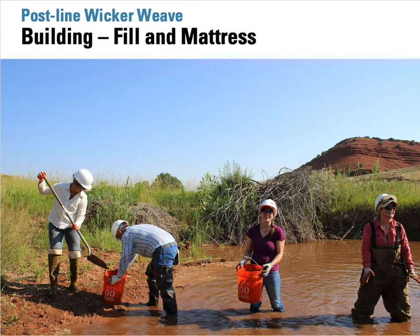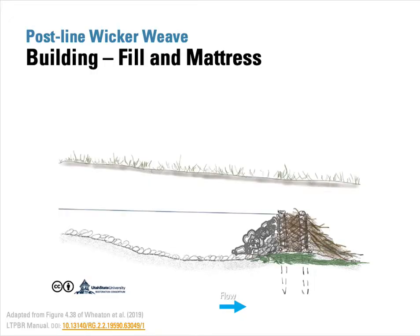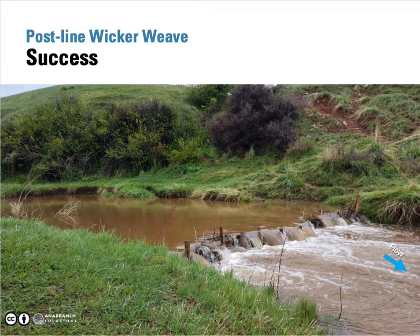And again, you need lots of dirt, lots of sod, lots of fill, so get yourself lots of buckets and lots of people. And here's an example looking upstream at a BDA in process, and you can see that they're integrating the mattress near the base as well, so they're building the mattress up as well as the weave. And then finally, you want your fill material to reach your desired crest elevation and get that even water flow across your structure. And here's an example.